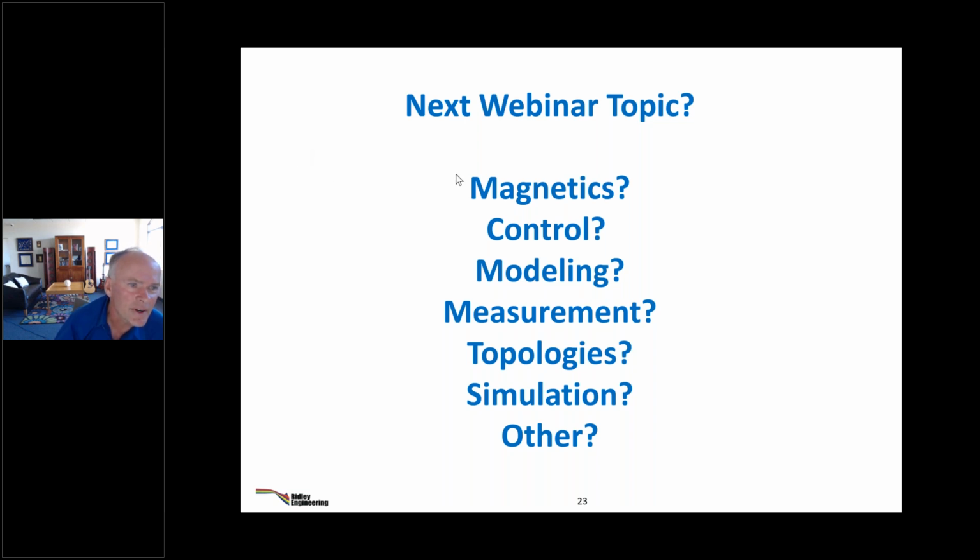If you don't have zero current switching on the secondary, you're going to lose some efficiency. Sure. Build it, try it. Nobody can answer these questions unless we're into your specific converter, your specific operating condition. That's when things start going different. If I'm not going to do zero current switching, how deep into non-zero current switching are you going to go? How much do you have to deal with ringing? How much snubbing do you have to put on? How much do you have to oversize the secondary diodes or the secondary rectifiers?